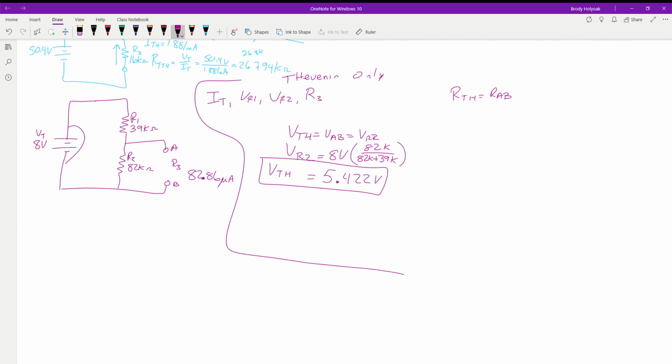The reason we do that is this voltage source, in theory, is supposed to have 0 ohms of resistance. It's not supposed to contribute anything to the resistance. It just spits out this amount of voltage, which we know doesn't happen. It has some. We've seen it when we measure resistance and we have it plugged in. It's going to change those values. But theoretically, it should work with 0 ohms of resistance. So this is why we have to short it.